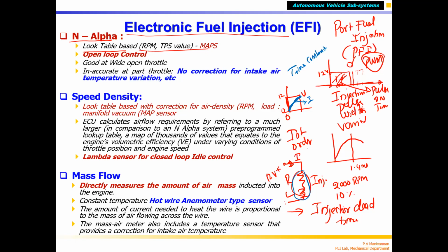The time constant depends on the resistance and inductance values. Correct? The time constant is proportional to the inductance and inversely related to the resistance. So if you have more inductance and less resistance, it takes longer to charge. That means you will get different time constants like this.